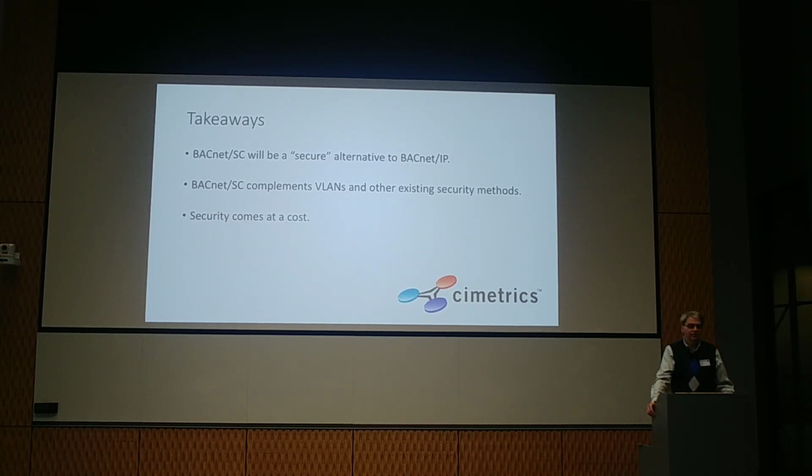Security questions for Jim. So you're using one cert for the whole site? Now, the idea is to have each device have its own certificate, but that certificate would be signed by a certificate authority, which would be managed either by the IT department of the site or by the primary controls vendor if the site doesn't want the responsibility. If you don't have individual device certificates, then you can't do individual device revocation.